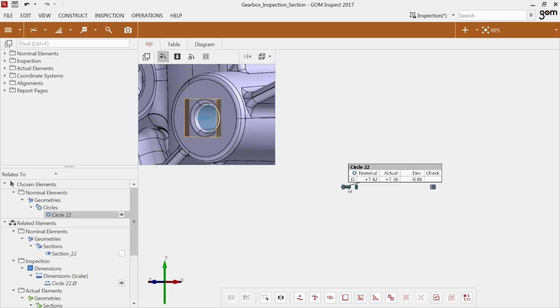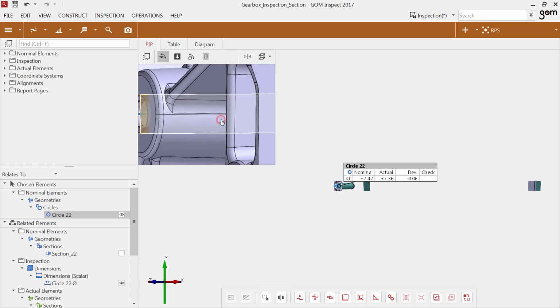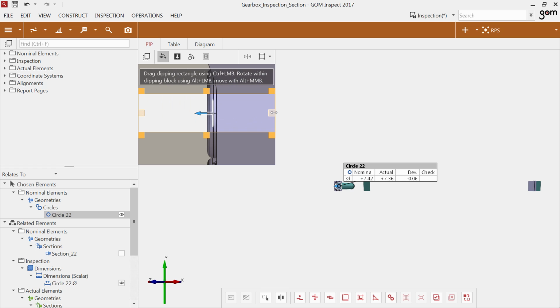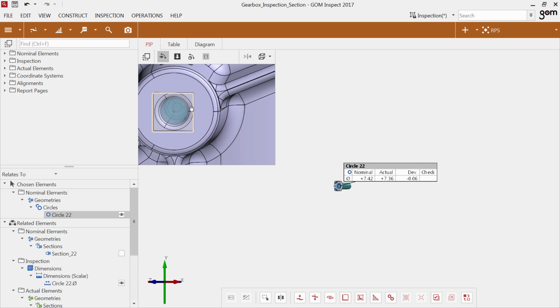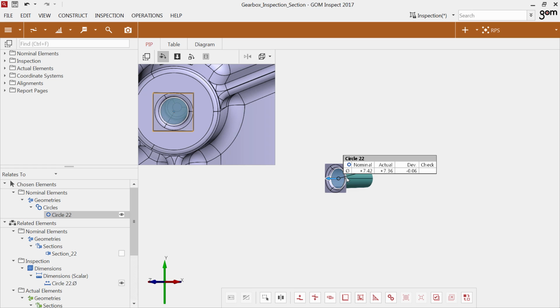In the 3D view, I can view the areas within the clipping block. As I just want to have this area, I will get rid of the area at the backside. To get the desired view, I can edit each clipping plane. After clicking a plane, I just drag a handle. I instantly look at the view shown previously.